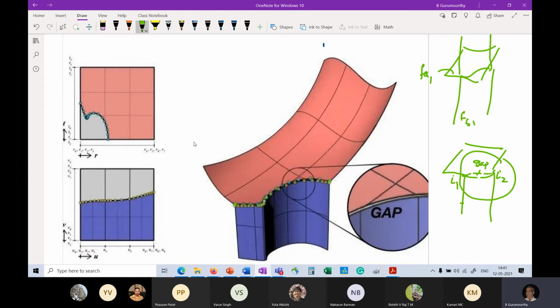So what people do is that they cheat. The way they cheat is that they create an entity called an edge, which is between these two points I1 and I2. That's the topology. But for the geometry, they store two geometries. One is an equation of a curve for the surface A, and one is an equation of the curve for the surface B. So that when they are drawing or doing this in one, they will use this equation, and when they are calculating for this face, they will use this equation. So that, from a validity point of view, because I1, I2 is only one edge, you will treat this as lying on both this face and this face, and so you will declare that the object is closed.